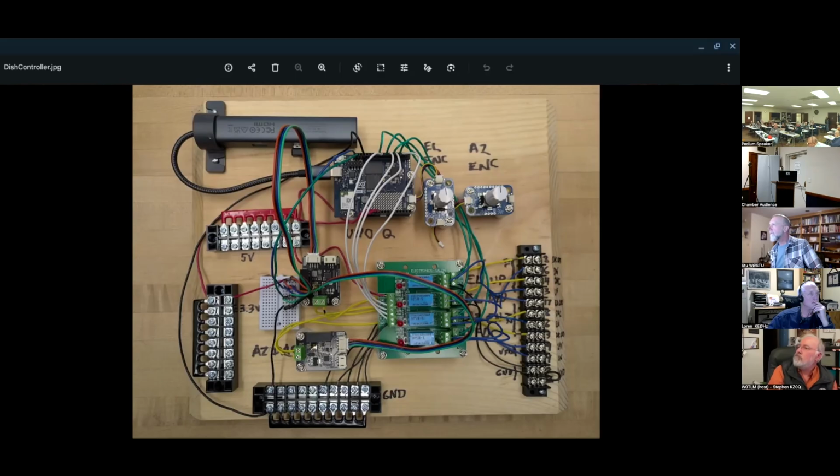Plus, what we'll do at that point in time is, instead of this analog -10 to +10 and all these signals, we'll actually start using the CAN bus or an RS-232 interface to drive the motors in the correct directions and at the correct speeds, which will pretty much get rid of everything you see down here in the lower left. It'll leave pretty much just the Arduino Q with a couple of USB to RS-232 connectors on it, or a CAN chip to run those. So we would simplify things quite a bit.